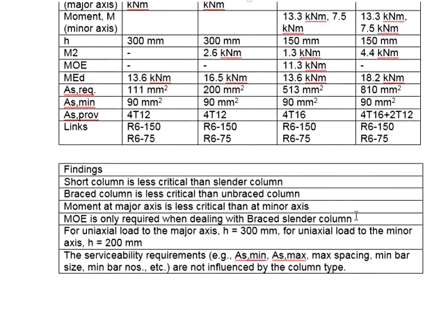So, if you can, maybe you should go for the short column. Unless, under certain practical considerations, you cannot make it a short column. For example, in industrial practice, sometimes the architect specifies the size of the column, or sometimes you will need to hide a column within a wall, which is not anticipated by the architect.